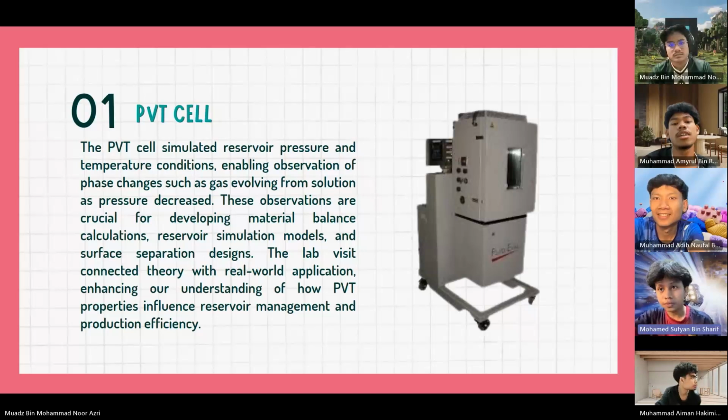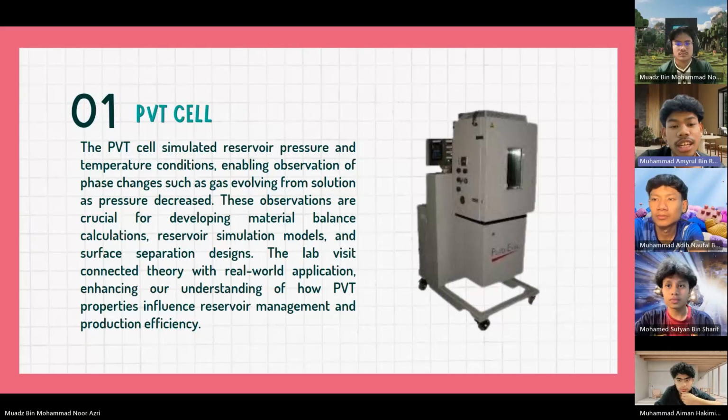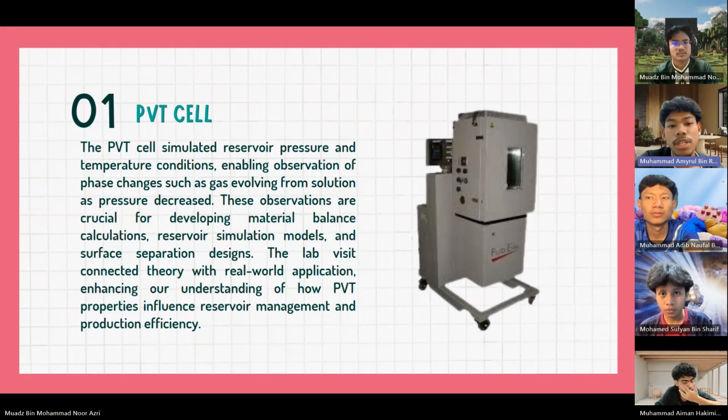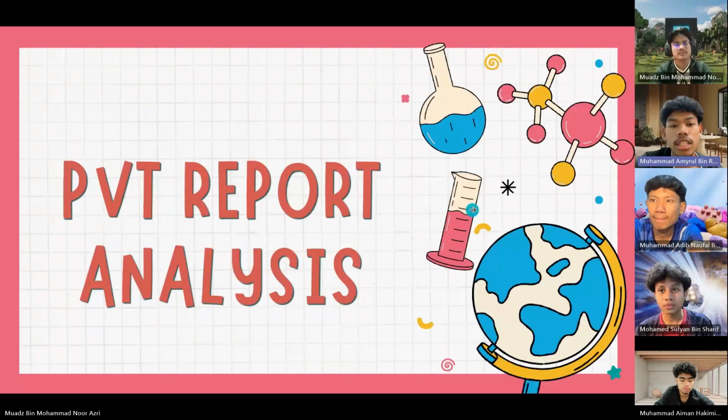So first of all, what is PVT cell? The PVT cell simulates reservoir pressure and temperature conditions, enabling observation of phase changes such as gas evolving from solution as pressure decreases. The lab visit connected theory with real-world application and enhanced our understanding of how PVT properties influence reservoir management and production efficiency. This is a little about PVT cell. And next for PVT report analysis, I will pass to my friend.